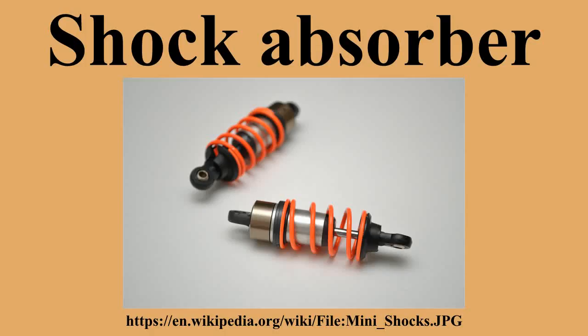Now, composite suspension systems are used mainly in two-wheelers, and also leaf springs are made up of composite material in four-wheelers. Early history. In common with carriages and railway locomotives, most early motor vehicles used leaf springs. One of the advantages of these springs was that the friction between the leaves offered a degree of damping, and in a 1912 review of vehicle suspension, the lack of this characteristic in helical springs was the reason it was impossible to use them as mainsprings.